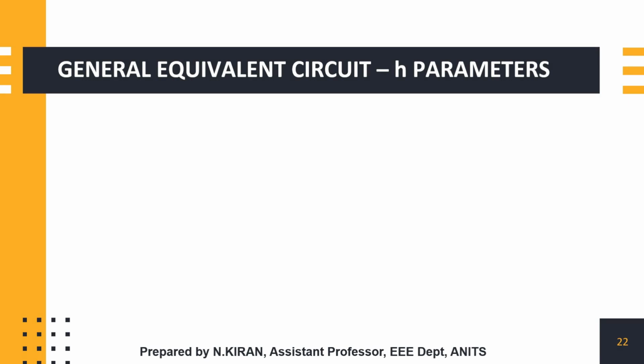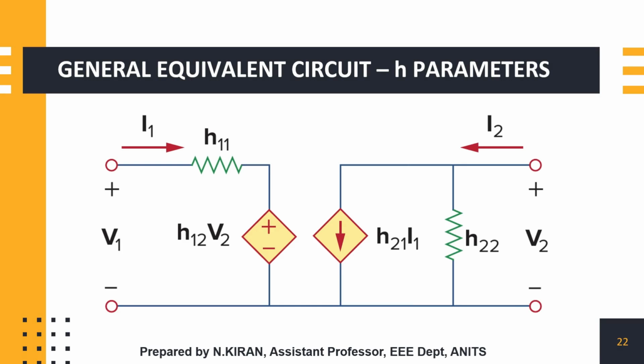So the generally equivalent circuit for H parameters is as follows. Using those two standard equations, if I apply mesh analysis in the first part of the circuit and nodal analysis in the second part of the circuit, I'll get those two standard equations for H parameters.